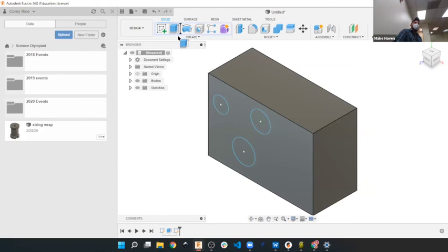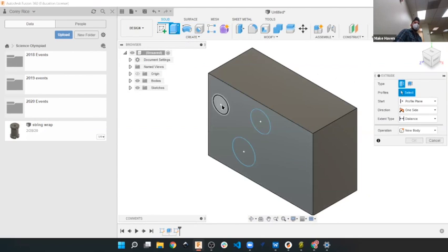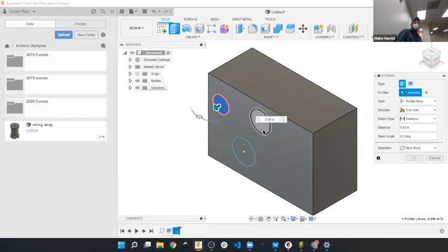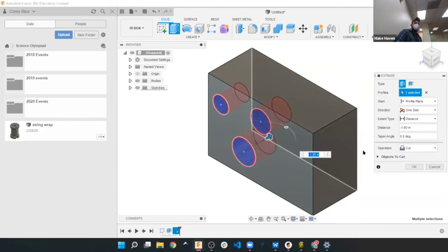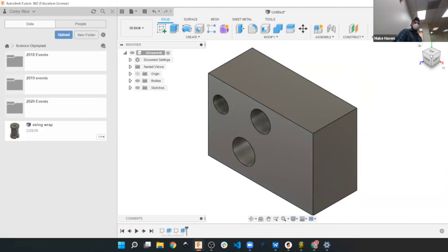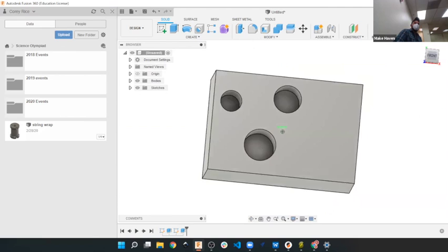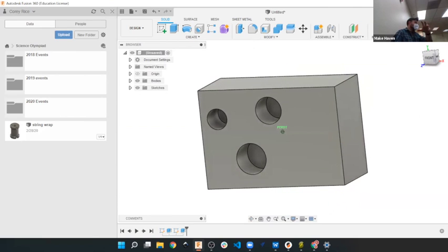And then you can stay up there. And then you can extrude these shapes again. And so it's asking, how deep do I want to extrude? I can do an extrude cut where it cuts away from those things. So sketches become things that you can use to squish 3D geometry into or out of existence from each other. And so you'll have to start to think about your shapes in that way if you're going to use one of these sketch and extrude design softwares.